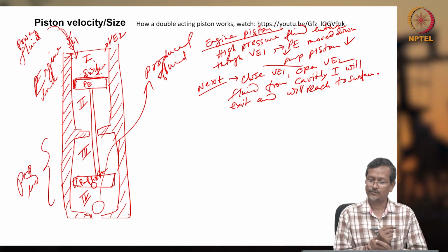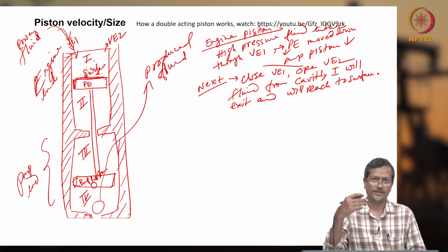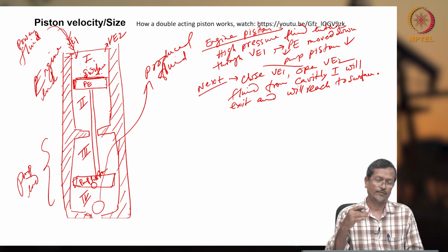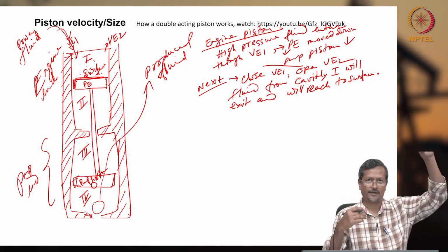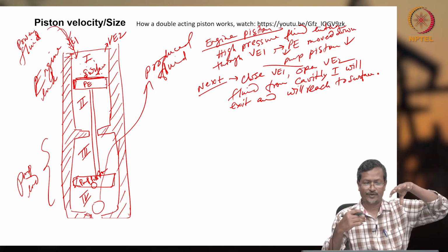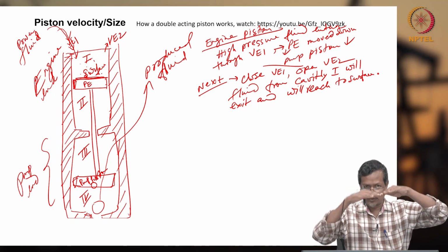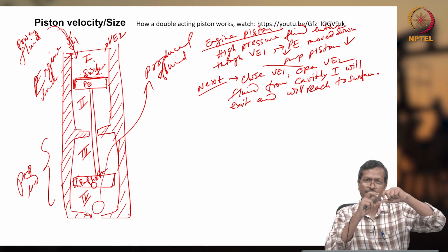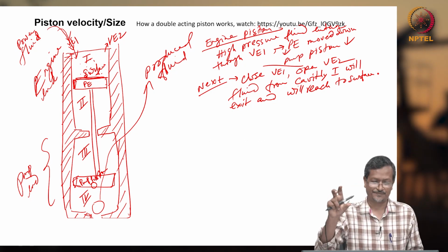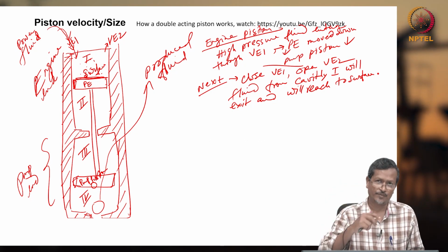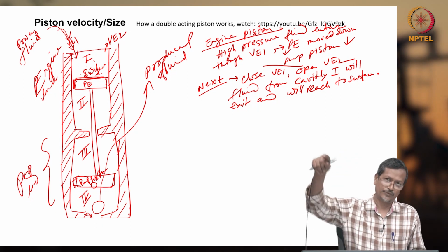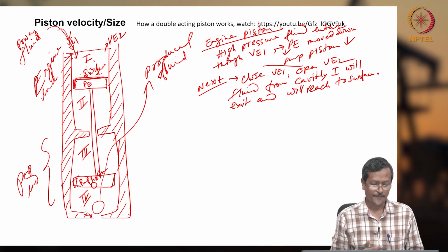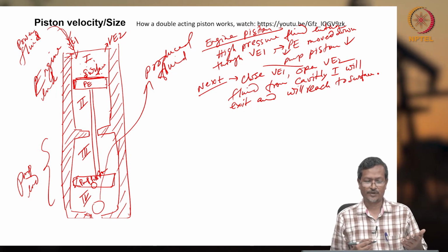Okay, so whatever fluid is exiting through VE2, through maybe different tubing, that fluid will have lower pressure. Let's say you have given 100 bar pressure, because it was pushing down the pump, so some pressure is already given to the pump. Now it has remaining low pressure. So that low pressure fluid will be moving up to the surface. Again you re-inject the same fluid and continuously that fluid will be going on. And on the pump side also the same thing will happen.